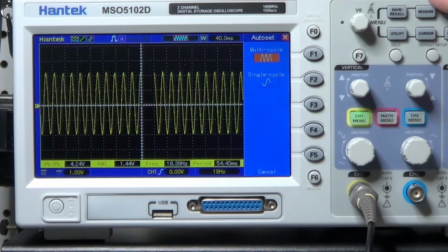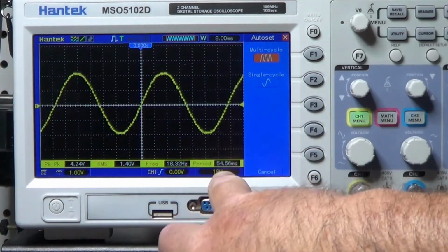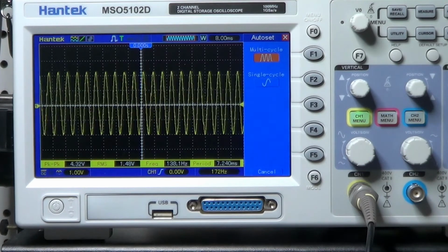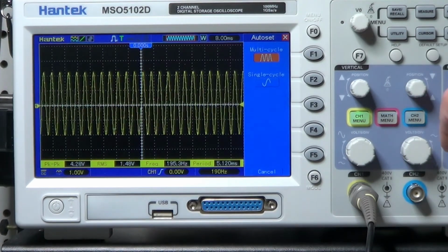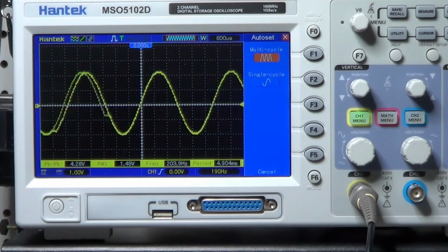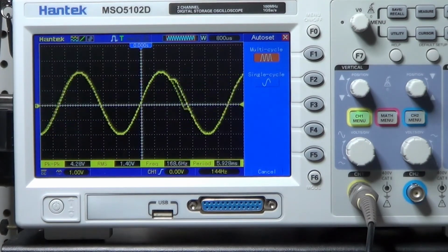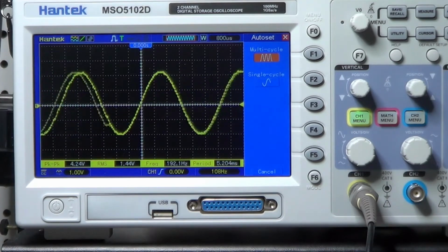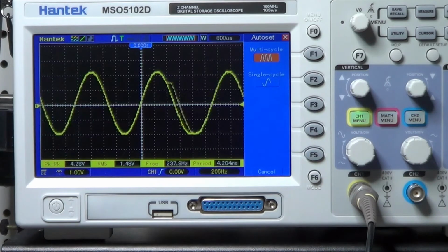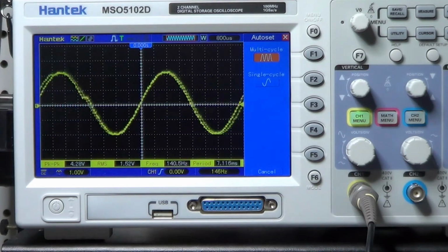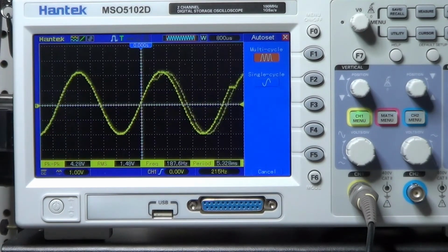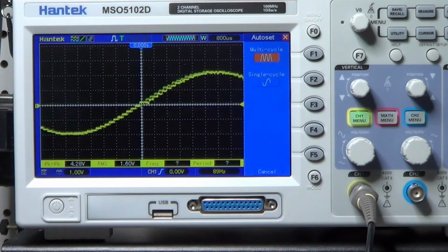And there is still a sine wave. This time it is quite faster, it's 18 Hz. And let me try now to move the potentiometer to see if we can do it better. Oh, look at that. This time I can actually change the frequency. So, the timer, along with the interrupt, have done something useful. However, I can see if I go up over a certain amount, I'm still having trouble. You see, I cannot pass the threshold of 200 Hz. Still very low, and if I move high enough, things get really weird.